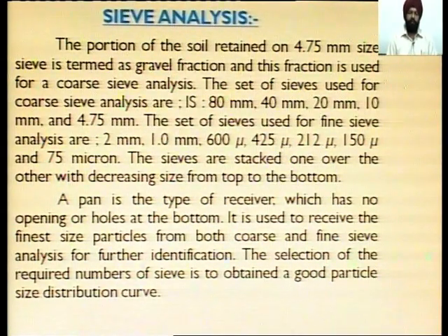Sieve analysis: the portion of the soil retained on a 4.75 mm size sieve is termed as gravel fraction, and this fraction is used for a coarse sieve analysis.